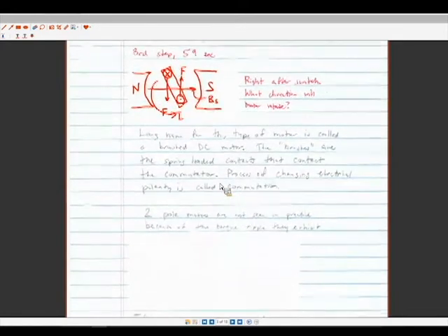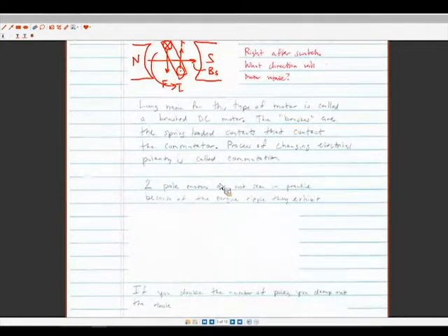Okay, so just some notes. The long name for this type of motor is brushed DC motor. They come in a variety of different forms. We'll talk about the parallel or shunt DC motor, the series motor, and a permanent magnet version of the motor. The one right in the middle, like I said, is the permanent magnet one. The one farther back is either series or parallel. We'd have to look at how it's wired up, because it's tough to tell unless you look at the path of the wiring. These are all in the realm of what are called DC brushed motors.